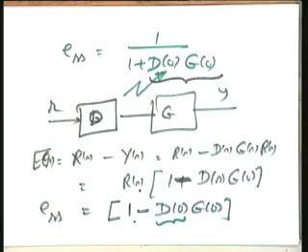So what I want to say is that open loop control has a solution as far as the dynamic response or steady state response is concerned. We are going for the feedback action primarily because of the sensitivity and disturbance rejection requirements, and those requirements are primary.